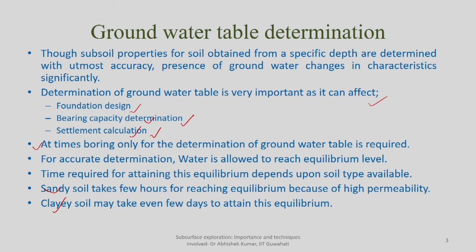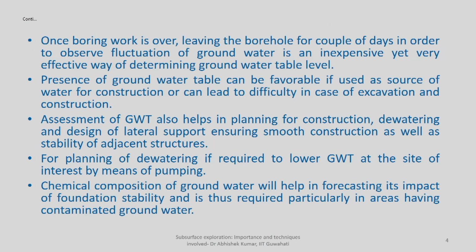So, overall the effect of groundwater table is important for settlement and bearing capacity determination, and in order to forecast proper bearing capacity and settlement behavior of the soil, you have to ensure the groundwater table, whatever you are determining, is not going to change. So, once the boring work is over, you have collected all the soil samples depending upon the depth you are targeting, 10 meter, 15 meter, 20 meter and more than that.